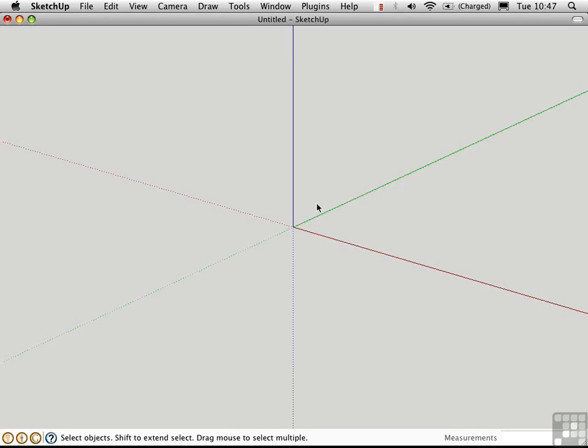You can use SketchUp Free to import the DWG file into SketchUp. Of course, it works in the Pro version as well. And then you can use all of the features in SketchUp to design the building. You could then chain that on to the first workflow that I mentioned. Then you take that model back into AutoCAD or Revit or some other program to create a more complete set of documents for a building.